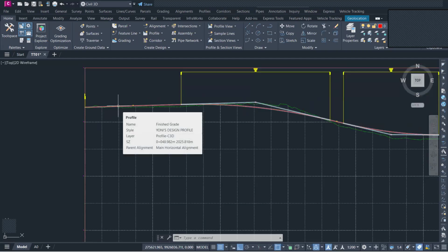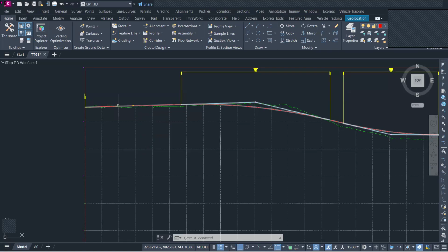The moment you know the final subgrade, that is when you generate your quantity takeoff. Once you're done generating your quantity takeoff there, you will then offset this to the final finished level. The final finished level is where you get the layers for subbase. So let's say our subbase is 150, our base is 150, our surfacing is 50. So that becomes around 350. So that is 0.35. You multiply again by our vertical exaggeration factor. Let's say times 10, some will even have 10, and therefore this will become 3.5 meters.